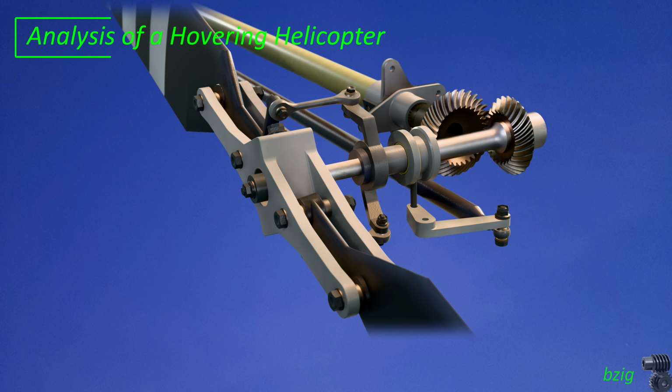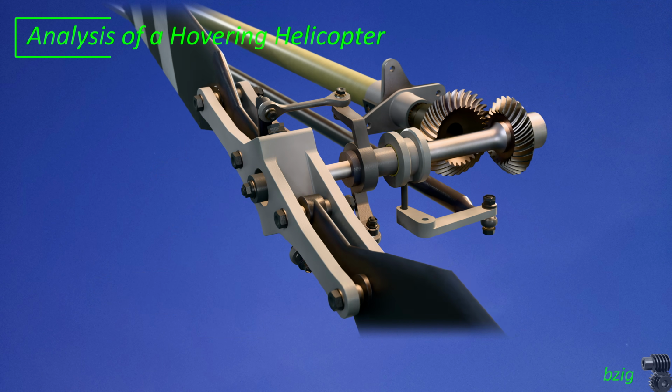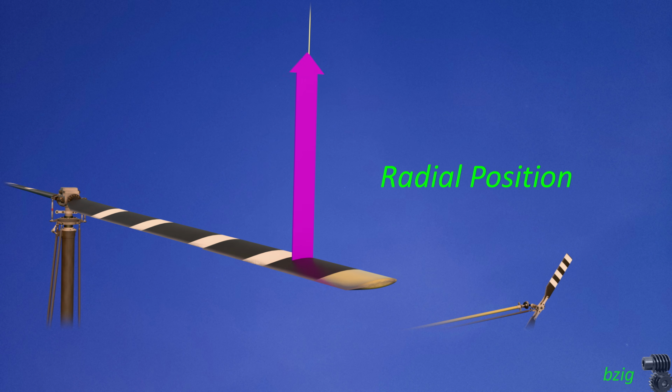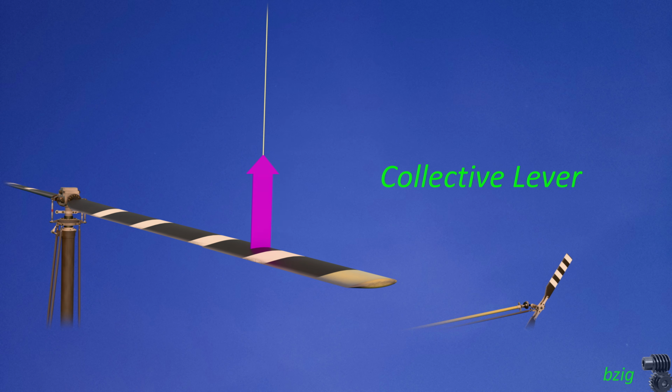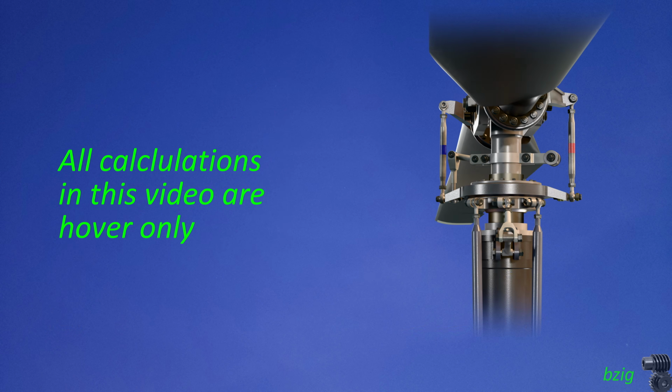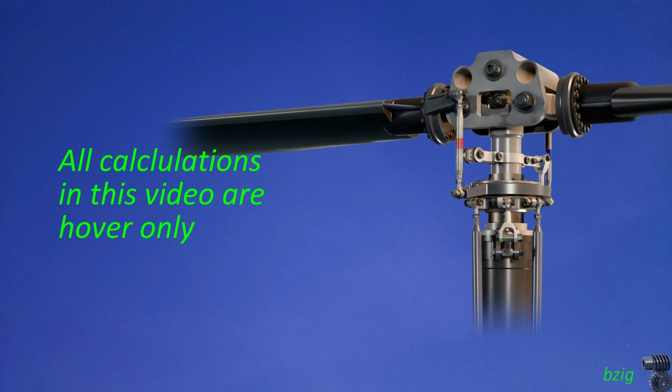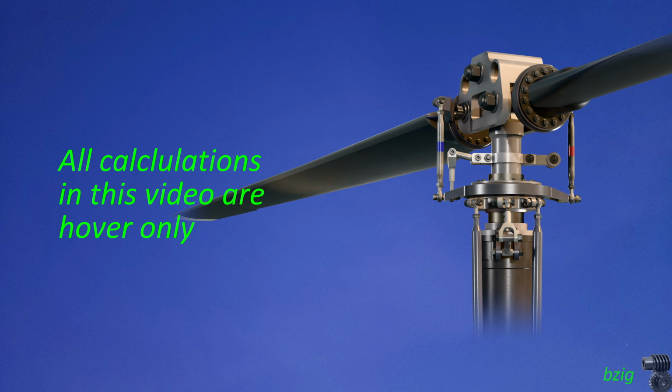This analysis gives a good insight into how helicopters work, and the most insight comes from observing the net aerodynamic force vector. As I change input variables in the simulation, the magnitude and direction of this vector changes. For a hover analysis, the most significant variables are the radial position along the blade, the collective lever position, and the vertical descent rate. I hope to take this to a forward flight analysis next to include flapping and forward flight dissymmetry of lift effects. For today, it's hover only.